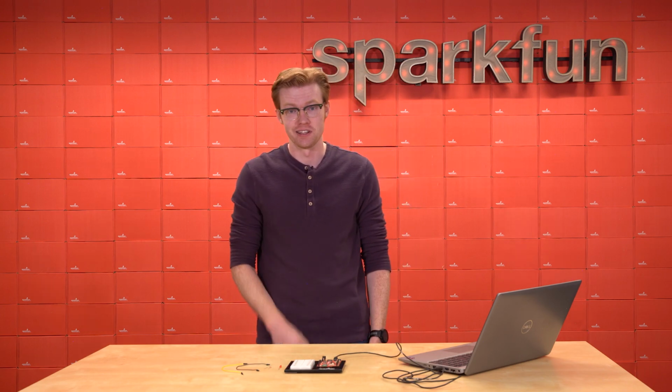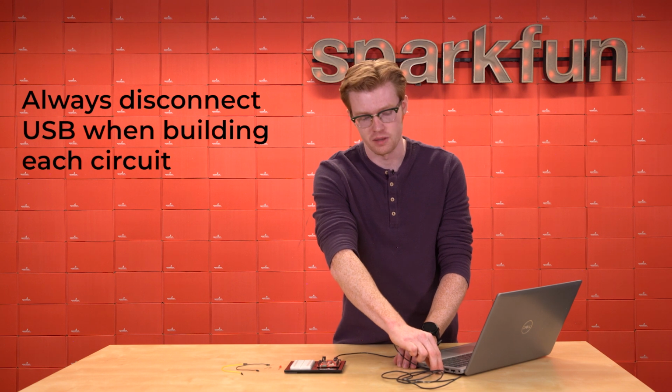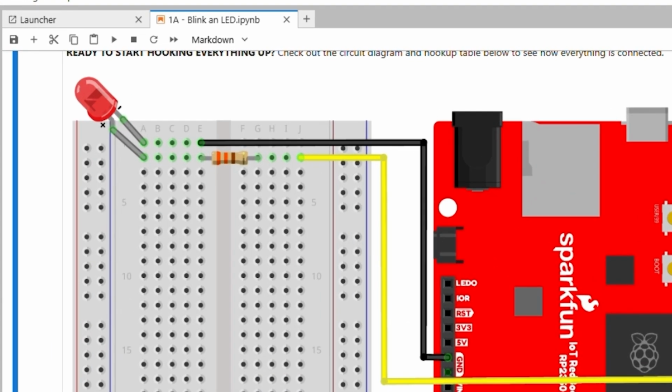Let's build the thing. Remember to always disconnect your USB-C cable before you start assembling your circuit to make sure that you don't damage any of your components. For the first circuit, we'll connect the long positive leg of the LED to A2 on the breadboard, the short negative end of the LED to A1 on the breadboard, and the resistor from E2 to G2. Direction doesn't matter for the resistor because it's not polarized.